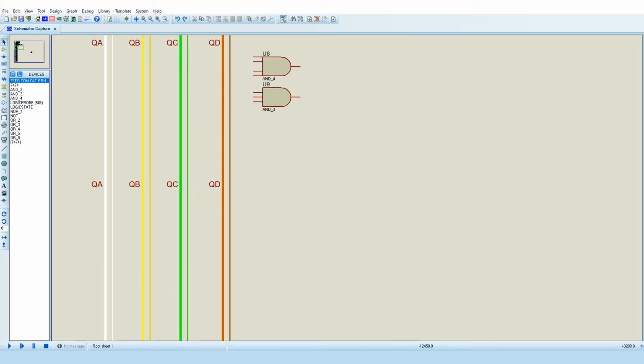Now segment B, which had a 4-input AND gate and 3 3-input AND gates. I'm going to use a NOR gate instead of the OR and a NOT because it saves us a gate. We don't need the NOT gate now. The expressions for segment B using the NOR gate as shown, DC not A or CB not A, so we just wire those up.